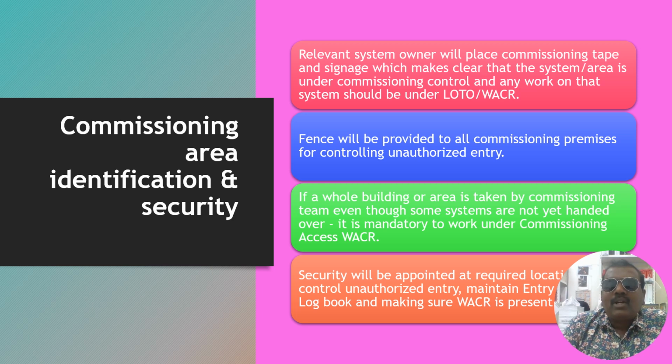Why? Because before, it was dead panels, now it is a live panel. There are power supplies available. So to control the system and to have a safe environment, we should consider that location as in the commissioning zone, so that the construction permit should not be valid for that location, and the commissioning permit system should be implemented in that location.